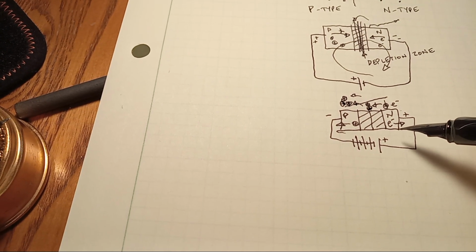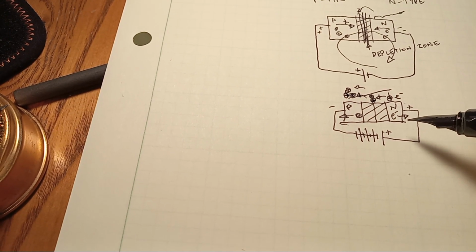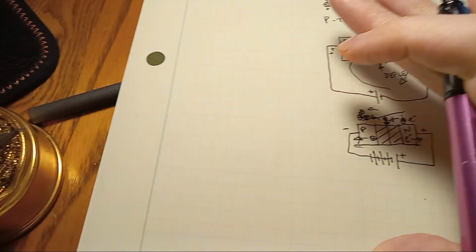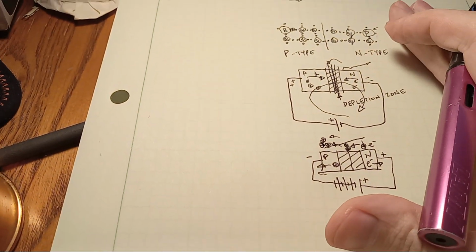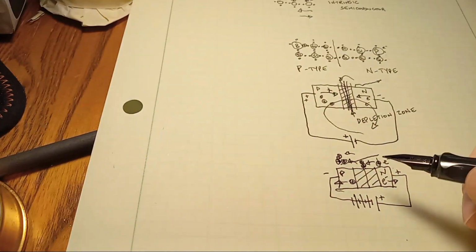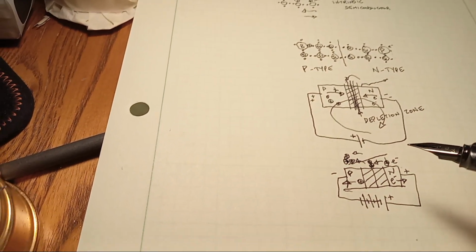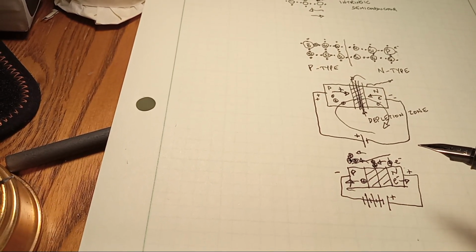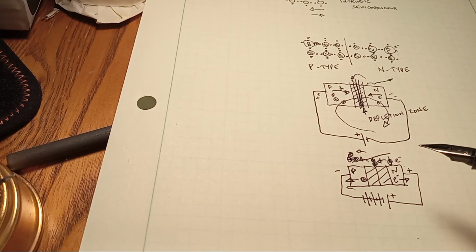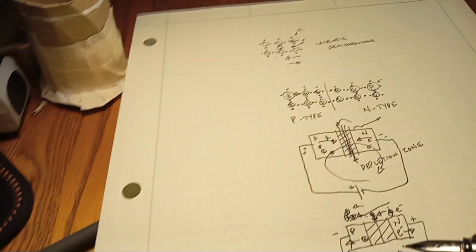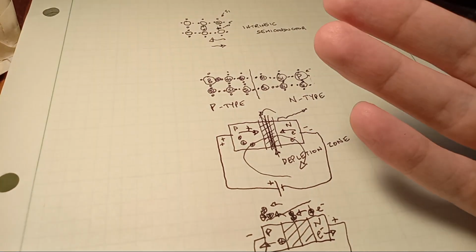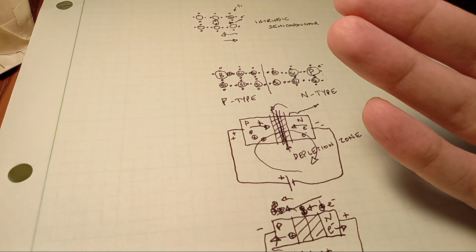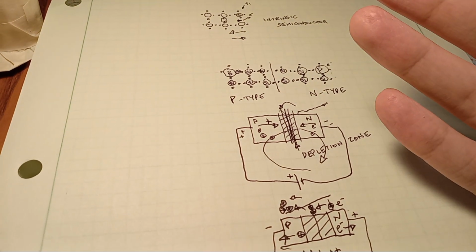If you reverse bias your diodes enough, you can force them to conduct. If you apply enough voltage, you can get anything to conduct. Don't you worry. You can get very interesting things with high voltage. Mineral oil will crawl up your wires because it is attracted to that which is inside. And why were you immersing your wires in mineral oil? Because the air will break down if you leave them in open air because of corona discharge.